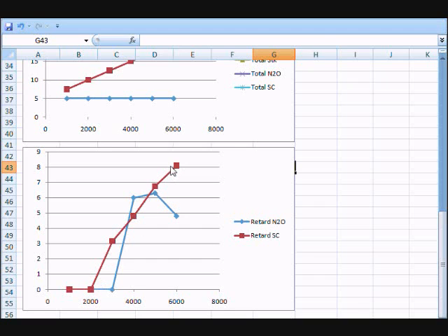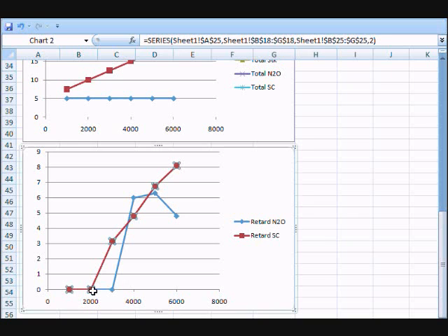If I go out and give 8 degrees of timing retard at 2,000 RPMs because the car is supercharged, then between 2,000 and 6,000 I'm going to be losing horsepower because I could have more timing in it, and I'm not. So with this little simulation you can figure out what your timing curves look like.